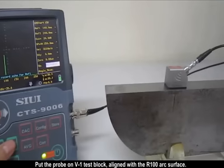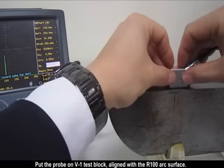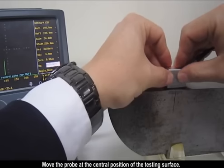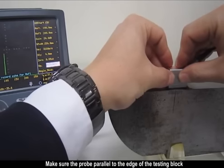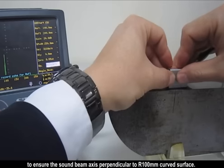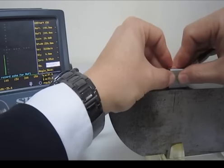Put the probe on V1 test block aligned with the R100 surface. Move the probe to the central position of the testing surface. Make sure the probe is parallel to the edge of the testing block to ensure the sound beam axis is perpendicular to R100 mm curved surface.